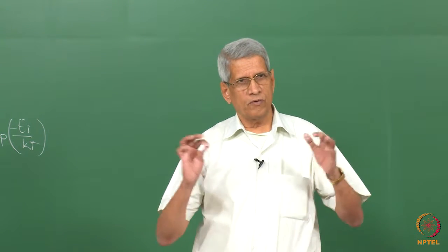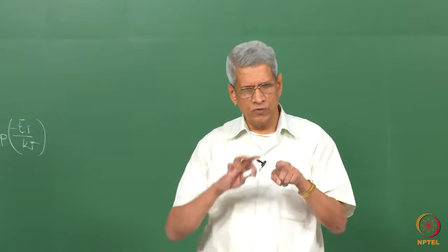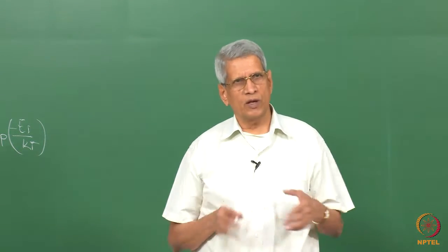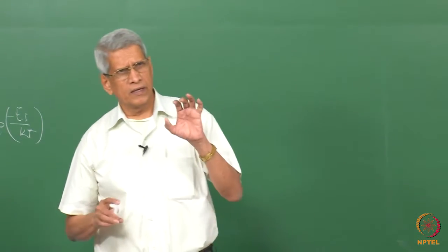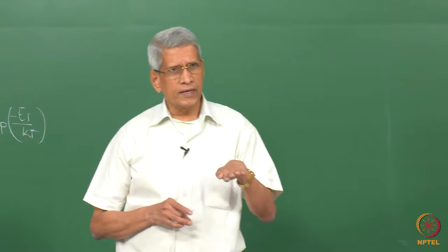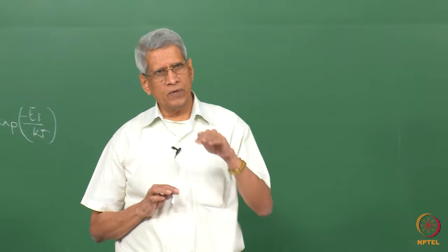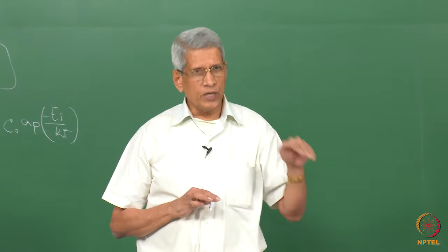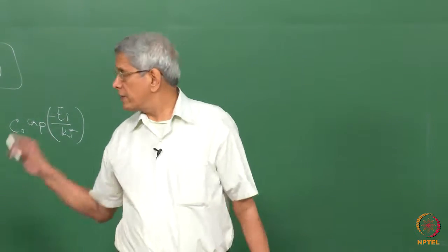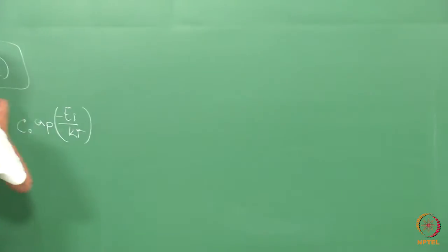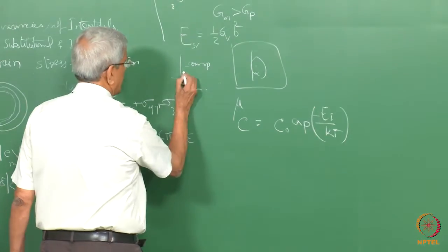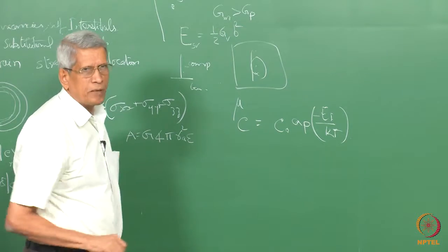That means there will be an atmosphere formed around the dislocation core. This happens because the temperature is such that the defect is able to diffuse. But at the same time, when the temperature is high, there is another process that can happen: the thermal vibration also increases with temperature.